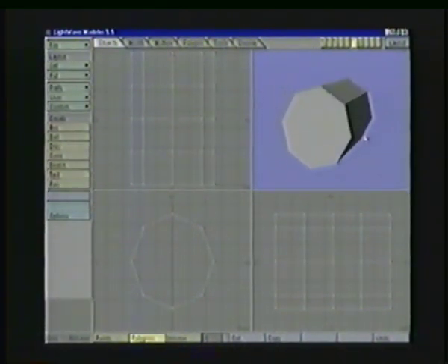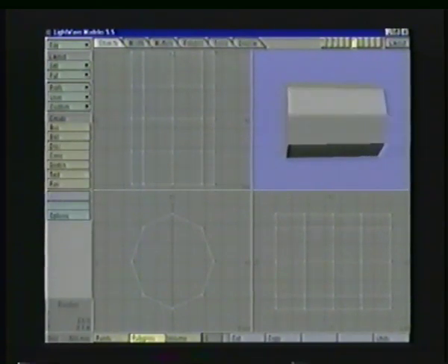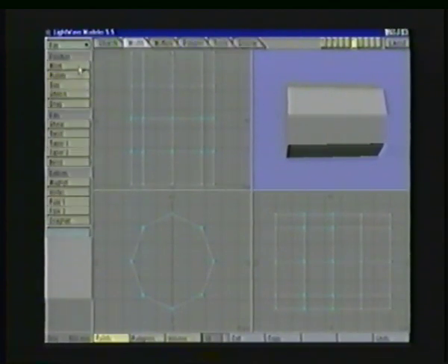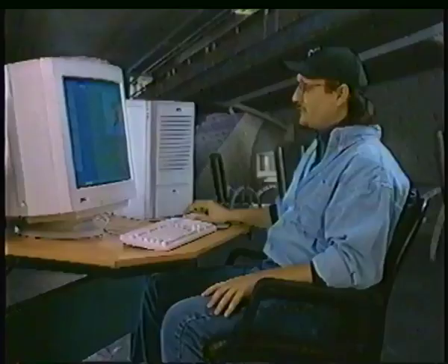Now there's the basic shape of the body that we've started with. This gives us something to work with. I'm going to select the 2 rows of points here in the middle, and then we're going to use the Move tool under Modify or T on the keyboard to move them down toward the rear of the body. I'm going to hold the middle mouse button or the Control key on the keyboard to constrain the motion so I don't move them up and down accidentally.